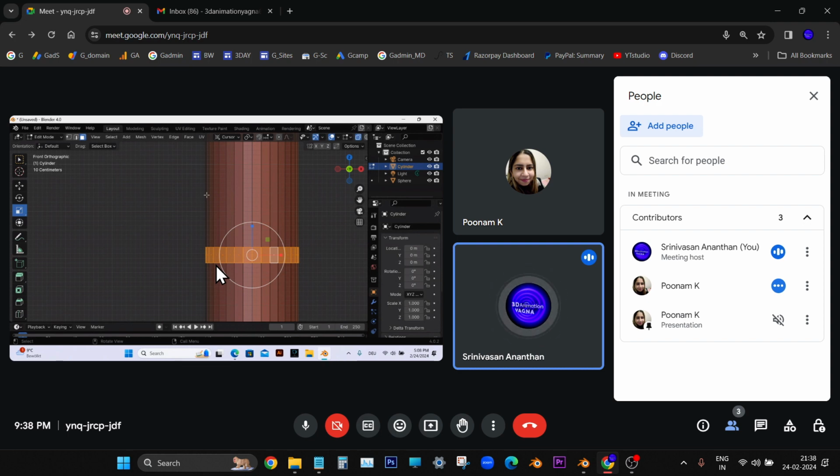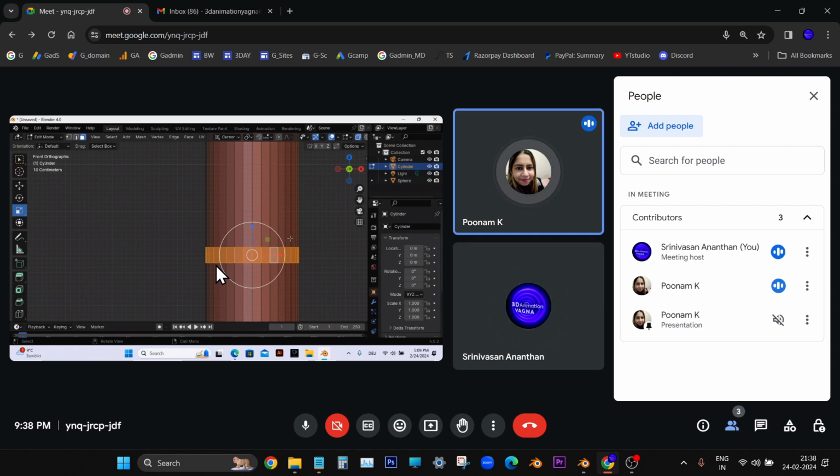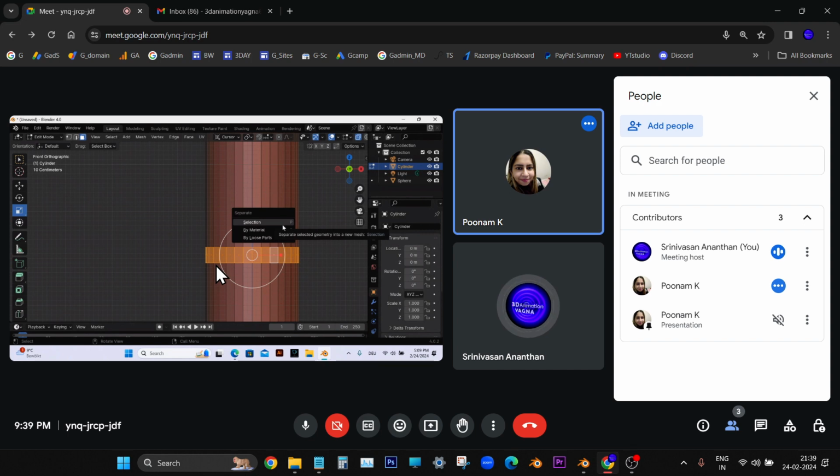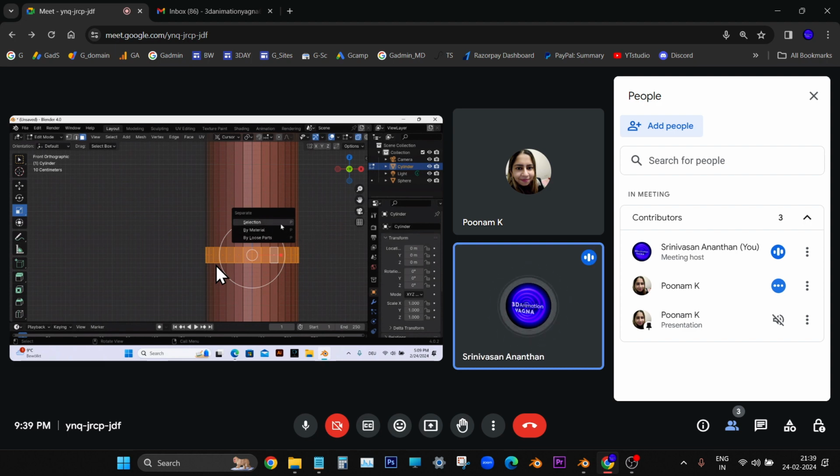Right now, we need this. We are going to cut this like a hot cake, and keep that object on the top, like that we are going to do. Now for duplicating this object and making it a separate object, just press P on the keyboard. It is asking which one to separate, whether the selected should be separated or it should be separated into loose parts. We are going to choose the selection. We have already selected the faces that we are going to separate.